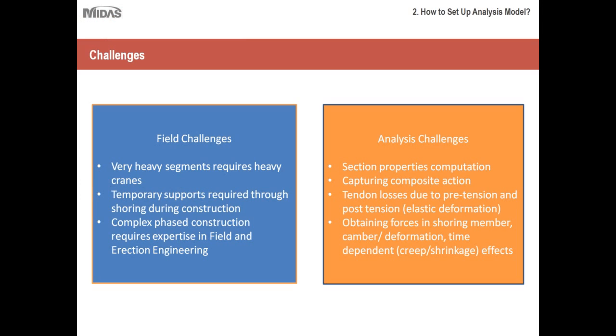Here we'll be going into the analysis challenges of these types of bridges. So the challenges could be categorized under two main headings. There are some field challenges, and there are some analysis challenges. For field challenges, like I mentioned, the segments are very heavy, so they require heavy cranes. Then you always require temporary supports, and for this you require shoring during the construction work.